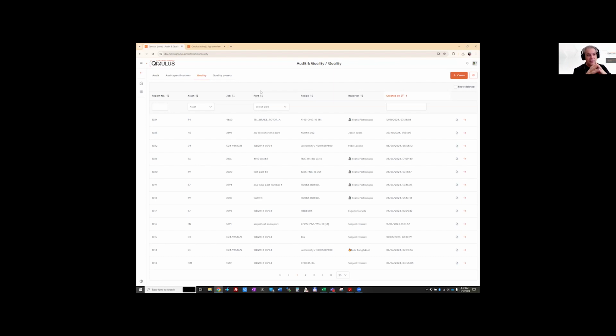One customer requires that I always check surface hardness. HR 15, check, done. 53 Rockwell, submit. So my report is one thing. Another customer might require surface hardness, white layer, case depth, and a profile.